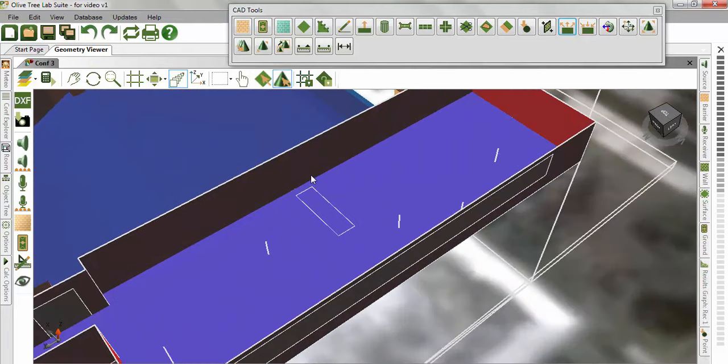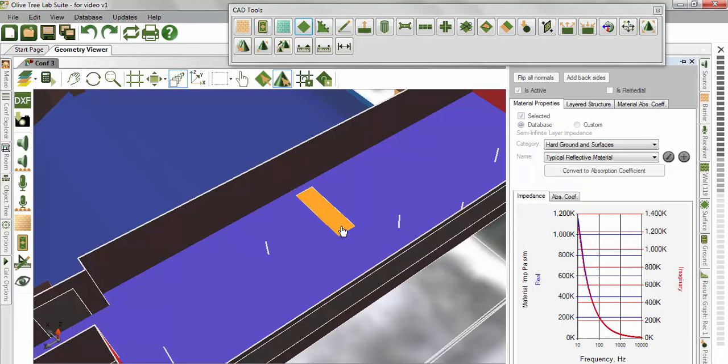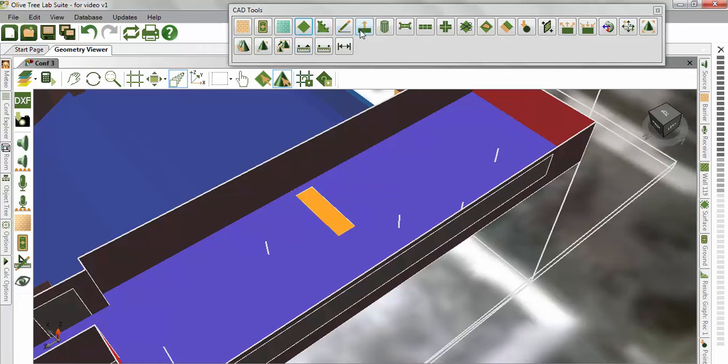Next, we're going to create the bookcases in the library. Using the Insert rectangle, click on the first 2 marked rectangle corners in the model and drag to the other end, and click once using the left click on your mouse. Extrude the rectangle surface using the Extrude tool and manually enter a height of 1.80 m and enter.